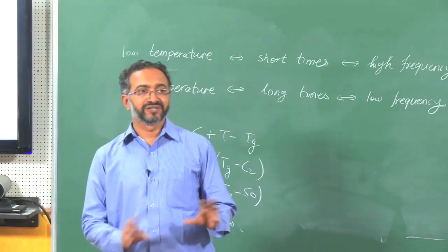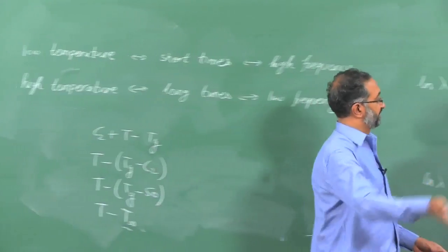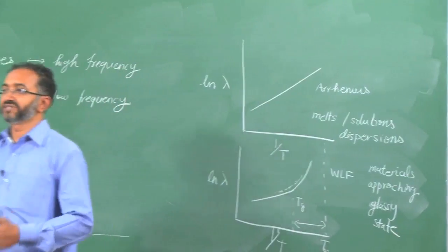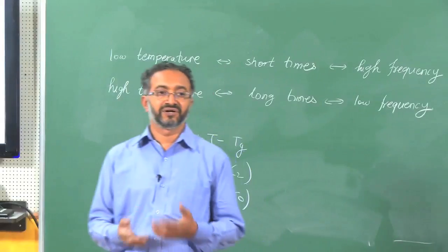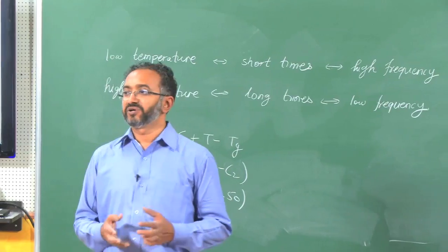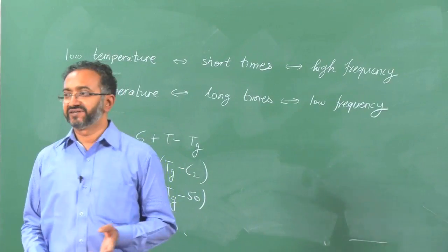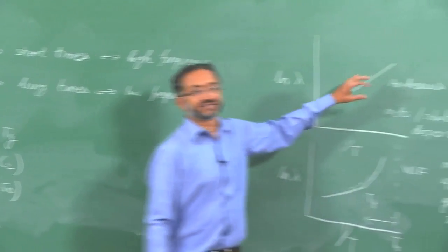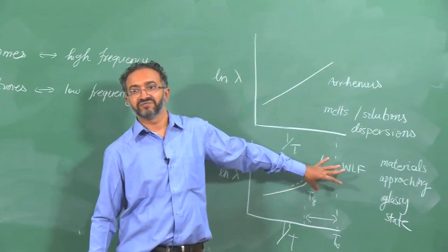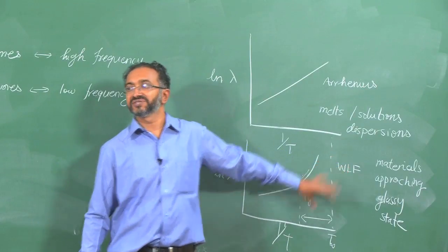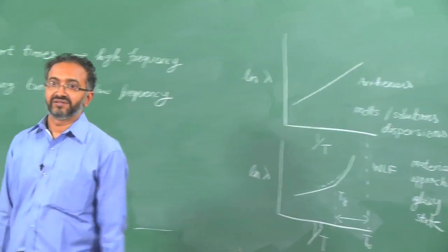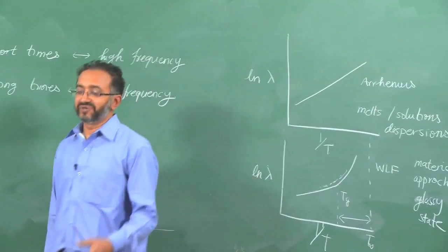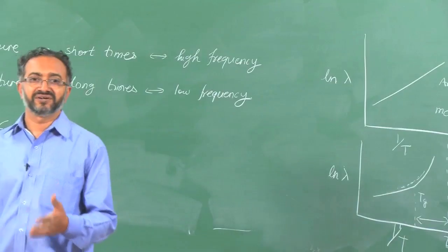And for a single polymer this is quite seen: for the same PET material, if I am trying to understand its viscosity and relaxation processes around 200 degrees Celsius, because its melting point is around 250, so around 180 to 200 degrees Celsius I can safely use Arrhenius, but around 100 to 110 degrees I will use the WLF equation.